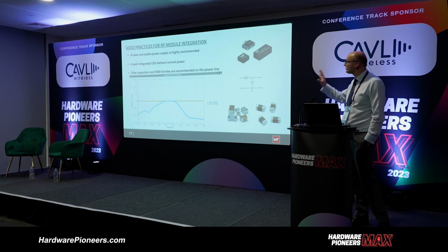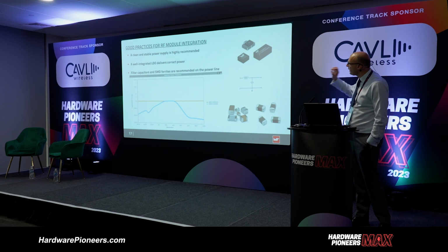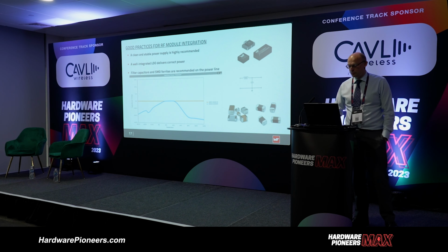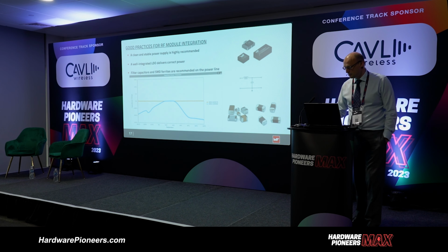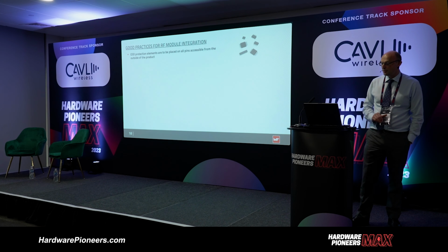So once again, all we're trying to do is give a little bit of a hint and a tip here that when you're using a pre-approved module, it's worth paying that little bit extra and going for those non-temperature dependent multi-layer ceramic capacitors.